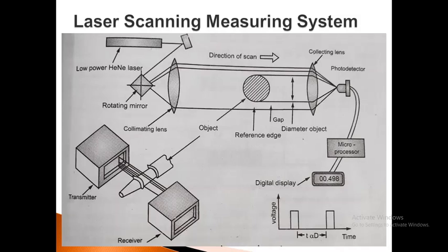The non-contact nature of laser scanning makes it well suited to in-process measurement, including such difficult tasks as the inspection of hot rolled or extruded material. And its comparative simplicity has led to the development of highly portable systems.